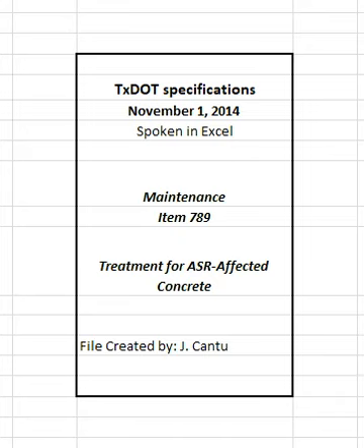4.3 Crack sealing. Seal cracks no earlier than 2 days after application of the surface treatment. Seal all cracks wider than 0.005 inches, 0.15 millimeters, with caulk. Seal cracks when the concrete surface and the ambient air temperature are between 40 degrees Fahrenheit and 105 degrees Fahrenheit. Place a small bead of caulk in a designated crack.